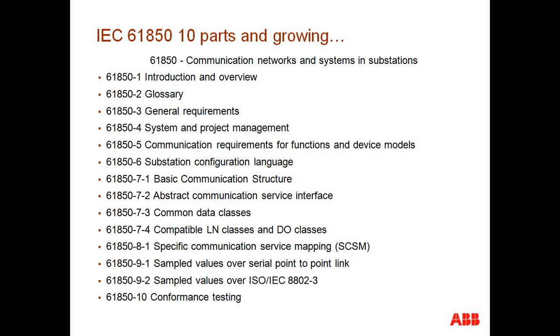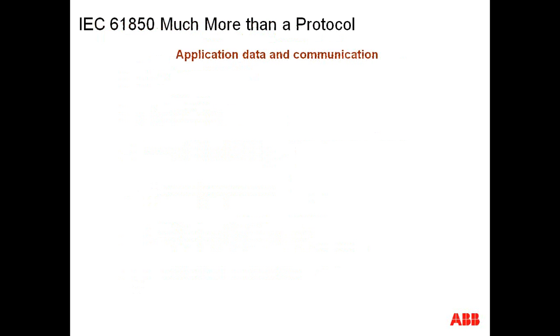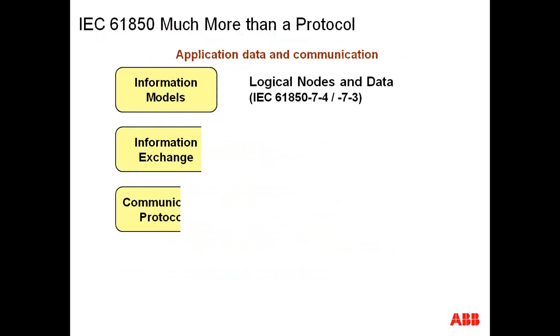And then number 4, there is a framework defined for the testing and the validation of such systems. So when looking at Modbus or DNP or other protocols, though, most of those definitely fall short on those 4 categories, and these are the gaps, though, that IEC 61850 is filling.